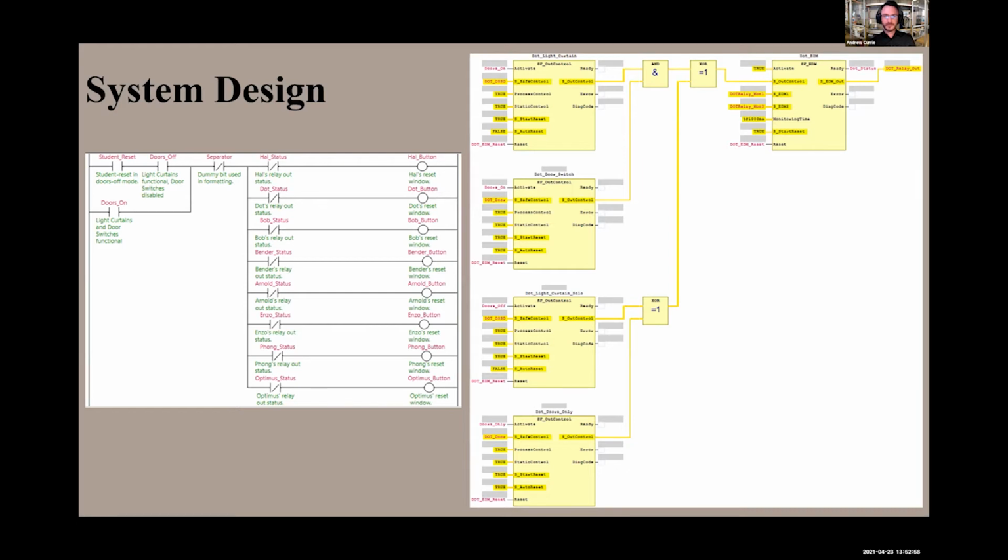To keep it flowing, the logic gets processed and makes it over to the safety function external device monitoring block on the right. Now, if all that logic is true, or the applicable logic to the selected mode, then a signal is sent to the relay within the robot controller saying it is okay for robot operation to proceed. However, if that logic becomes false, that signal to the relay also becomes false, and that triggers the auto stop functionality within the robot controller.